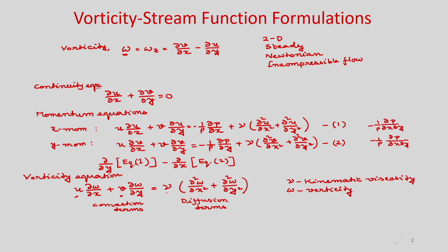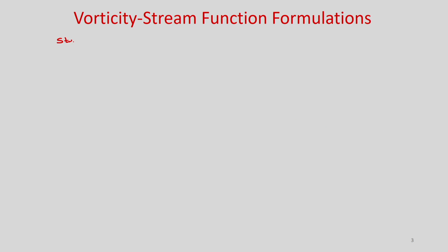So we define the stream function psi. It satisfies the continuity equation such that u is equal to del psi by del y and v is equal to minus del psi by del x. You can see whether it satisfies the continuity equation or not.